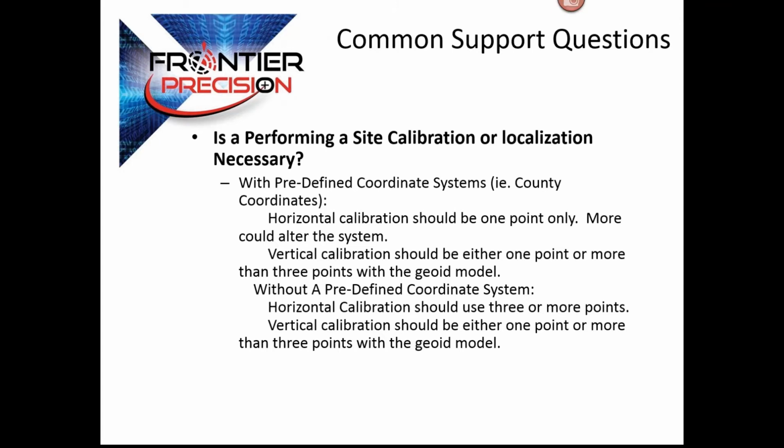Well, that doesn't guarantee that if I dial into this network in the middle of the state, my reference position is going to be relative to the vertical control that I am coming off of. In fact, 9 times out of 10, it's not going to be. It's going to be off. And we've seen anywhere from being within a couple hundredths of our vertical control point to 2/10 of a foot vertical difference. And that's not uncommon. And you would expect that.